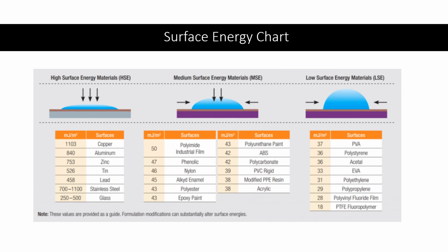Because that's going to dictate what type of bonding solution we're going to spec in based on what those materials are. And we always spec in a material that will perform on the low surface energy material. So when we're bonding two dissimilar materials together, say you're bonding mill finish aluminum to acrylic, we would base that choice off of a product that can bond well to the acrylic, because products that bond well to low surface energy materials also bond well to high surface energy materials.